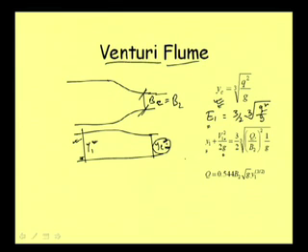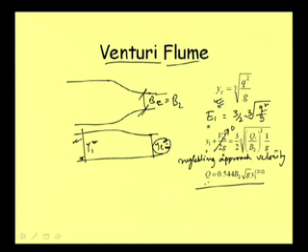So, now here if we neglect this approach velocity, because depth will be rising sufficiently, so velocity with which flow is approaching is almost negligible. So, neglecting approach velocity, this term will become 0, and then by just rewriting this expression we can have a form that q is equal to 0.544 B2 root g y1 to the power 3 by 2.